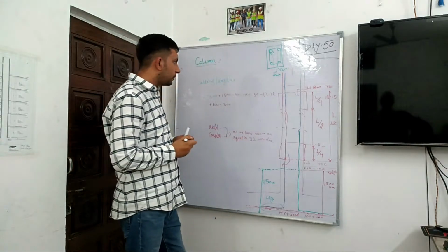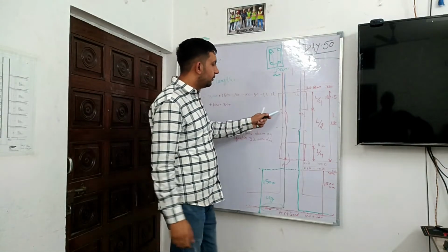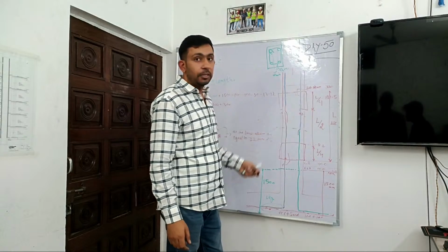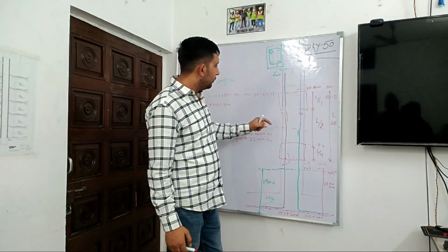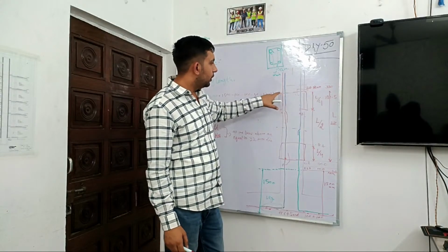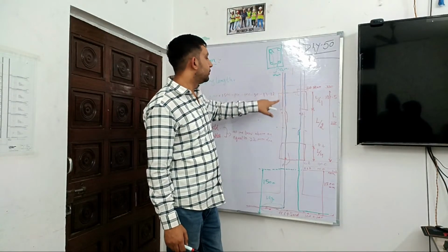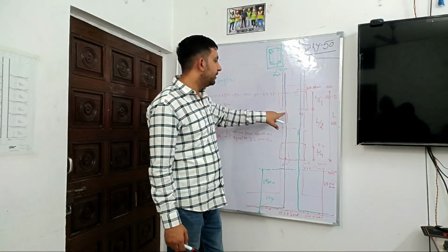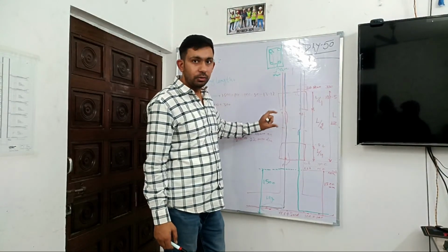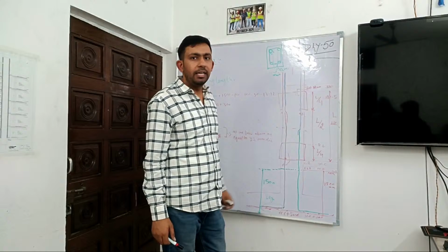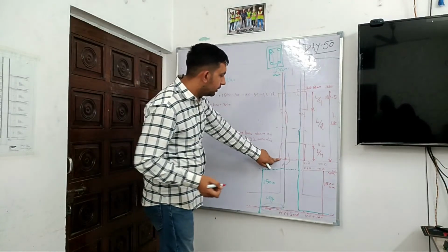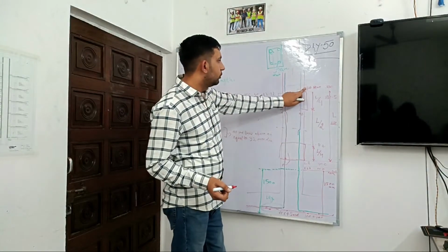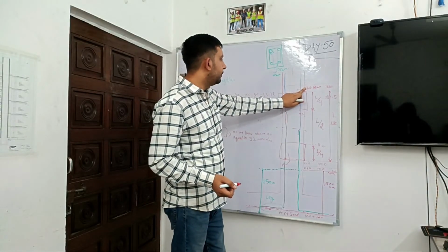Here, how do I have to reach here? Which path should I follow? Let's do one thing. We will go completely to the bottom of the slab, then subtract L by 4. We will reach here in the L by 2 zone, and there we will provide the lap. So after 300, how much should I get to reach the bottom of the slab beam?